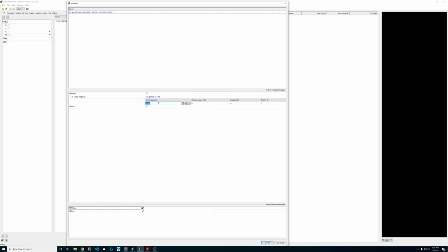So I'm going to commit to their profiling, and they've given me a depth of cut and a step over here too, which is going to be important in a little while. But for now, my two takeaways are that they want this tool driven on average at 610. This is in metric, so that's meters per minute on the surface footage, with a feed of about 0.166 per tooth. Now, if we walked away, any tool from 1 millimeter up to 20 is going to be driven by this data. That's not what we want. We want to be a little bit more accurate than that.